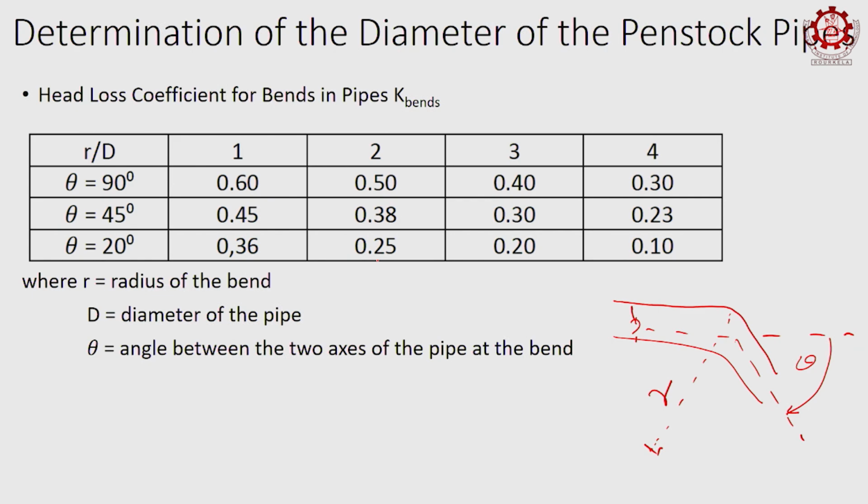So, you will have a number of bends in your penstock. The penstock will not be straight; depending upon the land profile it will have both horizontal as well as vertical bends. You can't route it in a straight line, there will be many difficulties in that. So, depending upon the land profile, I will show you some photos later on, at each bend you can calculate what is the offered loss coefficient.